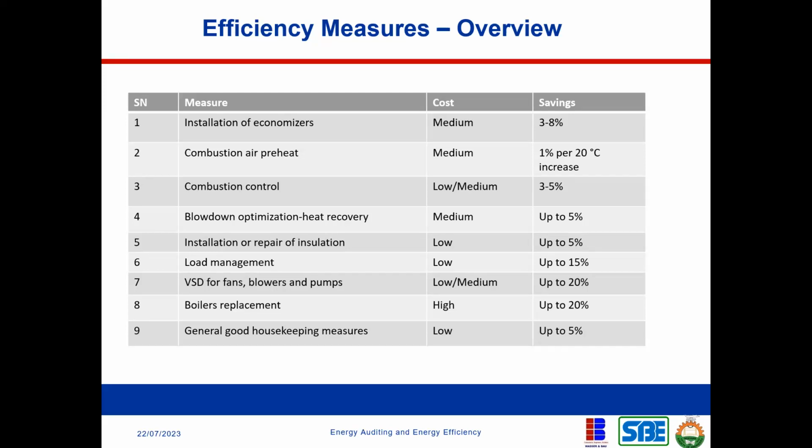But the one thing I want you to take away is that you cannot recover all the heat in that flue gas. If you recover all the heat, you create problem in that boiler. So you could recover the heat up to maybe about 150 degrees centigrade. If you go below 150 degrees centigrade, something is going to happen in that boiler that could create problem for that boiler. But there are other forms of technology that could be used.